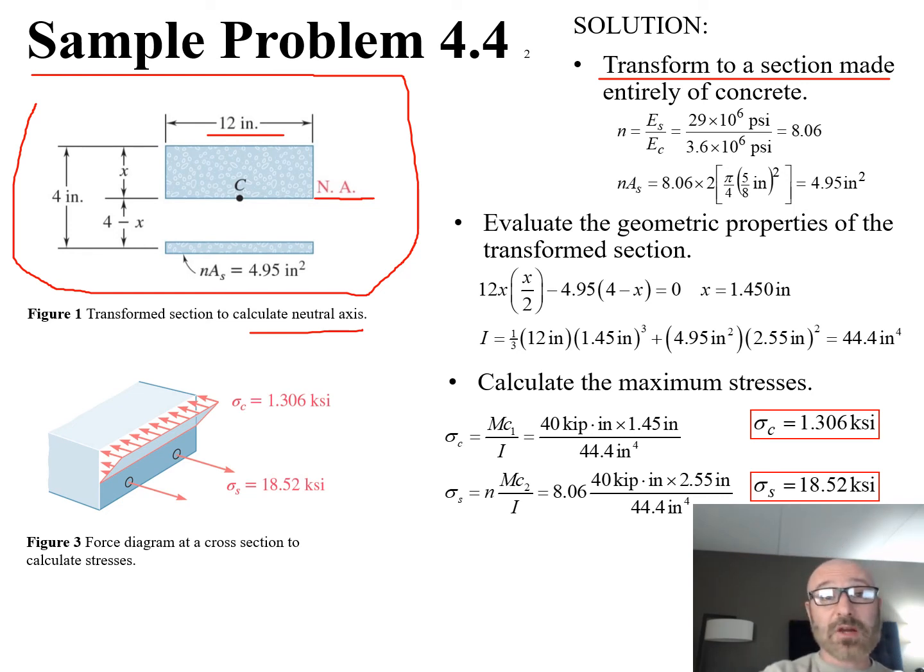And we have this shown below in figure 3 to calculate this. You can see there's a rebar right there, there's a rebar right there, that's 6 inches between those, that's 3 inches there and 3 inches there. So 6 plus 3 plus 3 is 12. So that's how we're drawing this out and solving this problem. That's where we're getting the 12 inches from, and that's going to come into play in a little bit while we're calculating the area of the steel as well, because there's 2 rebar involved in this.